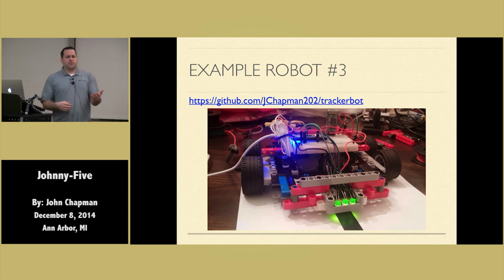So you had a question about the Yun, I believe. The Yun only has 64 megabytes of RAM. So if you do npm install johnny-five, it'll die on you while trying to compile node-serialport. To work around that, I had to find a pre-compiled version compatible with the Yun, download that separately, load that pre-compiled module into Johnny-Five, and then use that. Because there's only 64 megabytes of memory, there's a lot less power in a Yun than you get with a Raspberry Pi or a BeagleBone. A BeagleBone has 512 megabytes of RAM and a 1 gigahertz processor, so it's very different computationally.